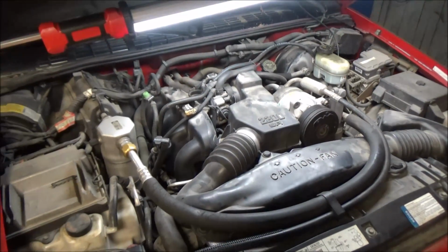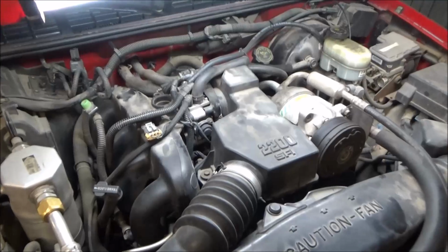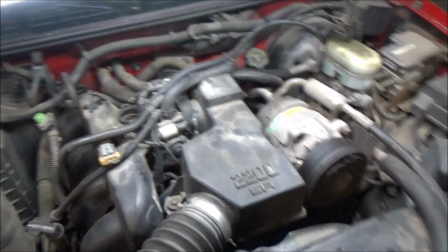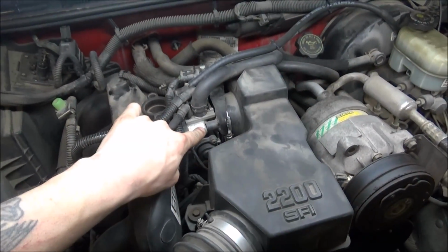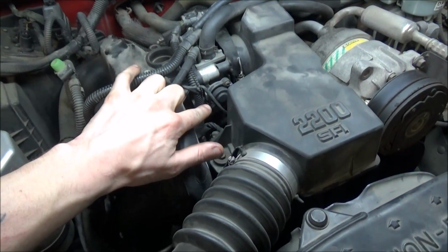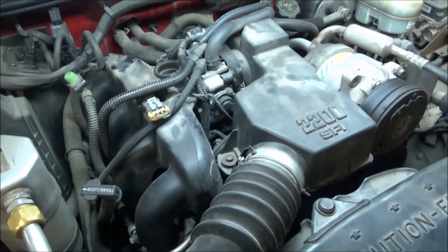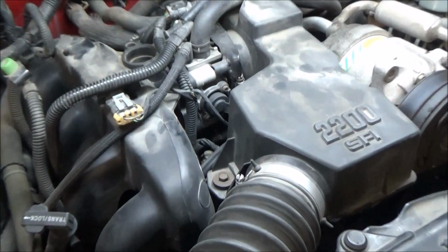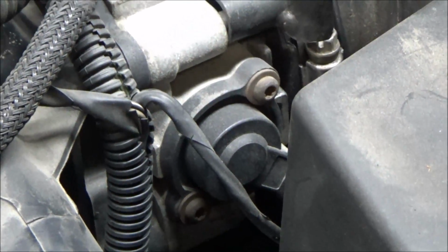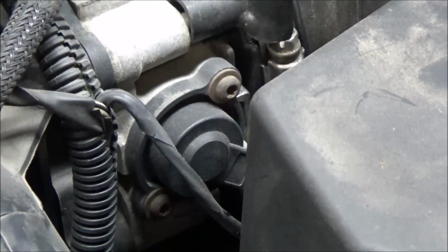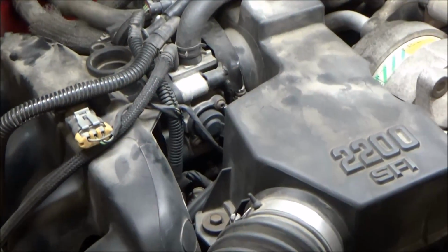Alright guys, we're staring at the front of the truck here, and I want you to have some idea of where this sensor lives. If we look on top of this, we can see this unit right here. This is the throttle body. If we look directly where I'm pointing, I'm going to get you zoomed in on it. That little disc-looking doodad there with the 2 screws, that's our throttle position sensor, guys, and that's what we need to be testing.